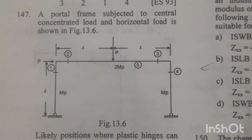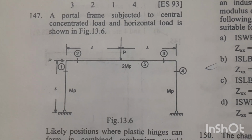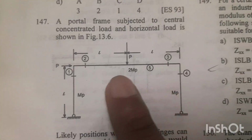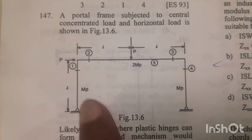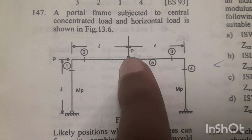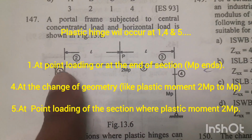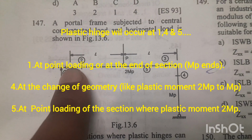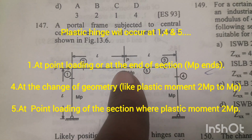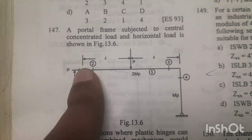Question number 147. A portal frame subjected to central concentrated load and horizontal load is shown in figure 13.6. Likely positions where plastic hinges can form in combined mechanism would include... So in this portal frame the plastic hinge will occur at 1, 4 and 5. These three positions, because the plastic hinge will occur at the point load, and at the change of geometry, like 2 MP to MP or MP to 2 MP. So this point will be valid.